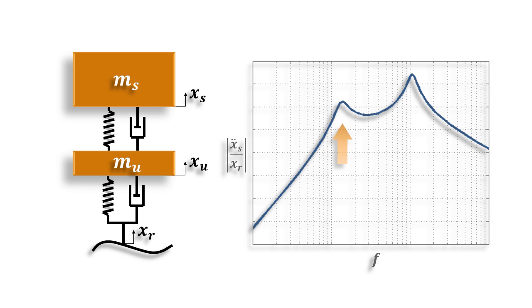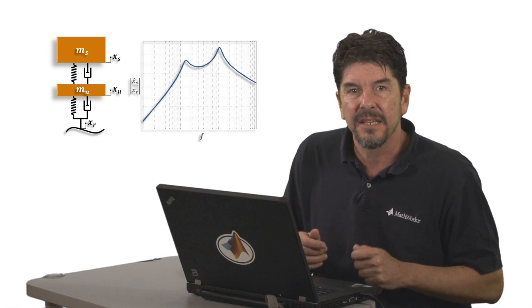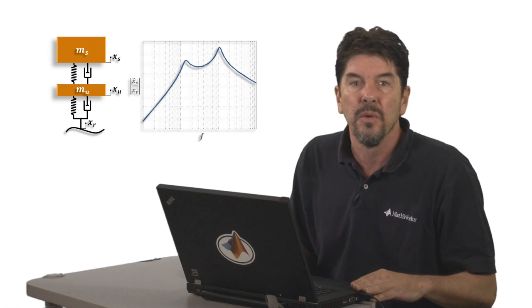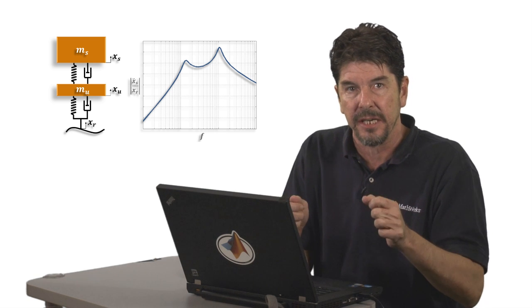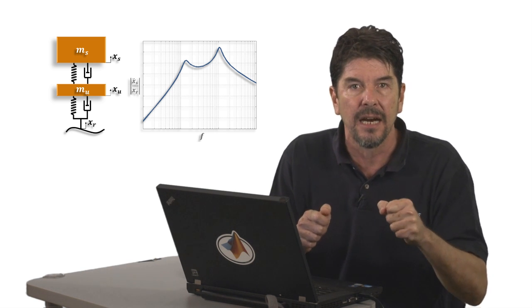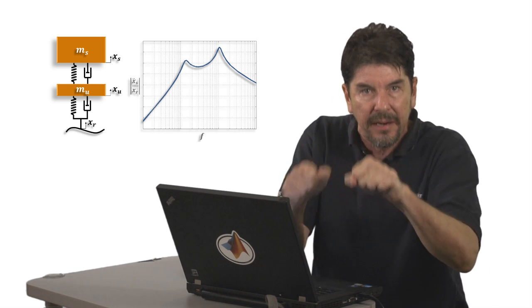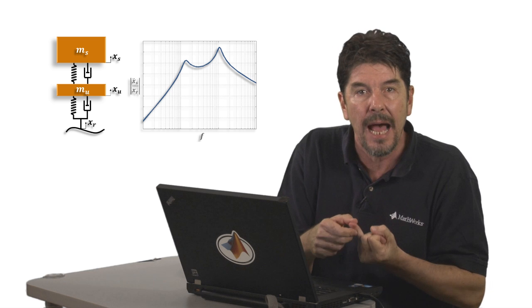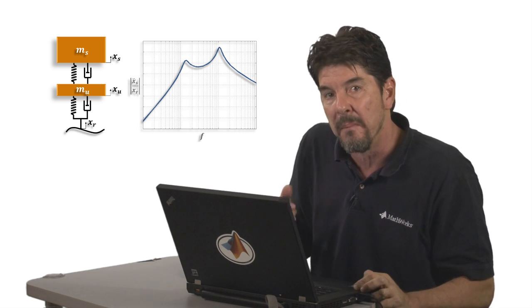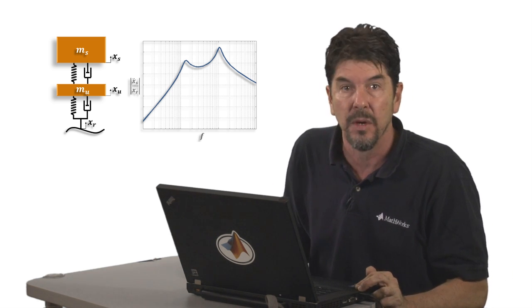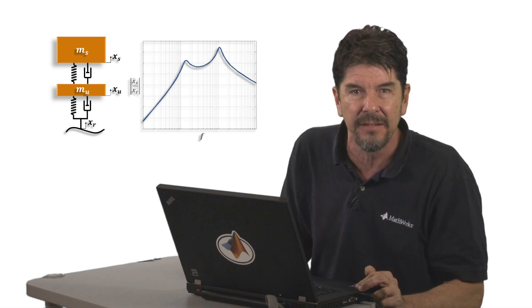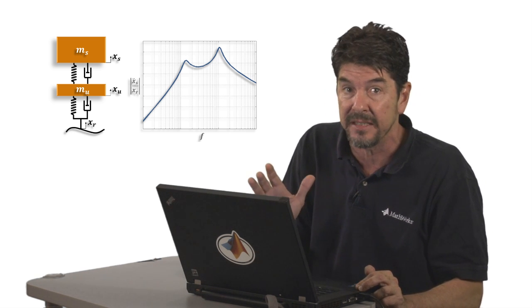Actually, what we're looking at here is pretty typical behavior of any standard car suspension. The first peak corresponds to the resonant frequency of the suspension itself, and the second corresponds to the resonant frequency of the tire. Has anybody ever wandered off the freeway onto one of those rumble strips on the emergency lane and felt the car begin to shake so bad that it felt like it was going to fall apart? No? The reason why that happened was that the speed of the car combined with the road profile underneath was generating an excitation that was probably very close to the resonant frequency of the tire.